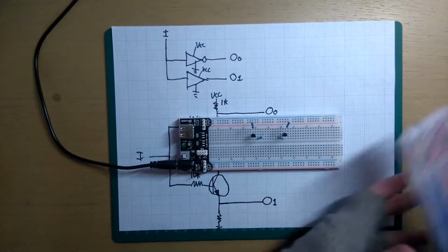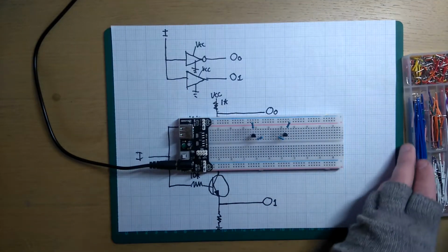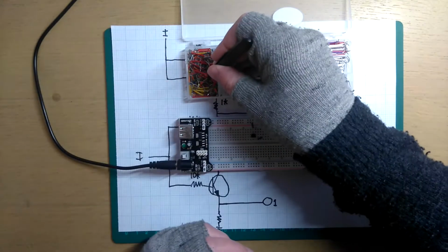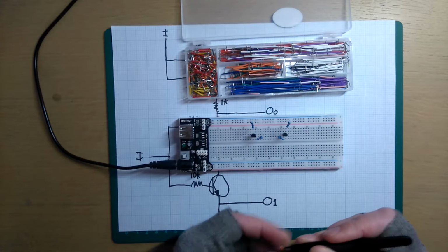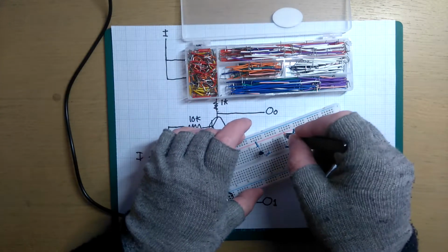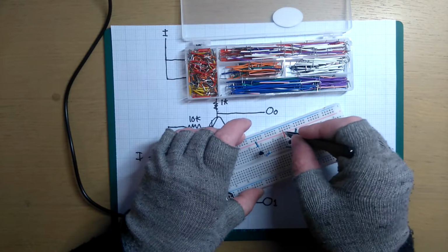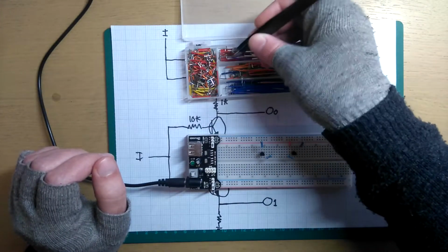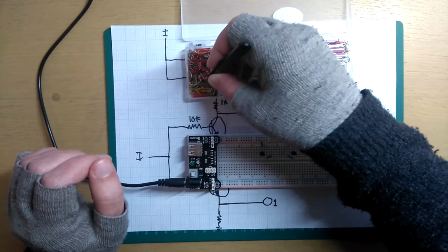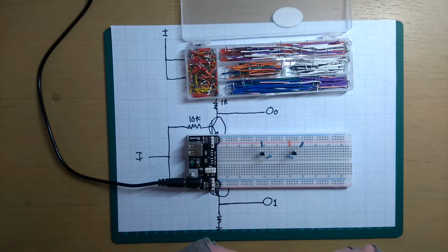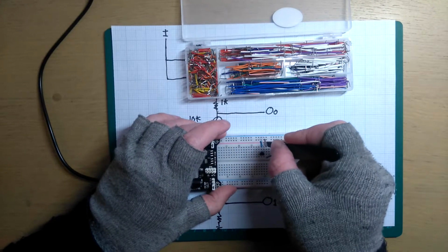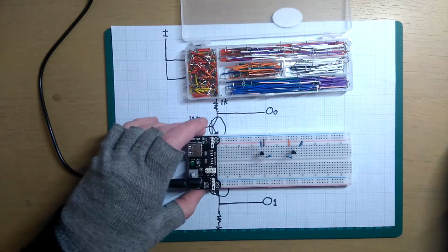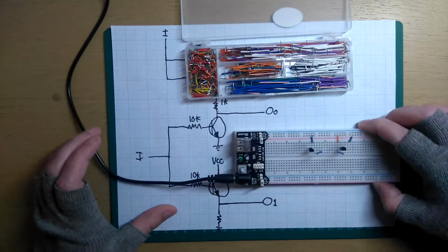We need to still tie them directly. So here's my tweezers. Let's get a couple of these little ones. So the buffer needs to be tied directly to the VCC. That goes there. And a slightly bigger one for the ground rail here. It's slightly further away. Yeah, so this one here is tied to ground rail. Missed the hole slightly. There we go. So those are our buffers.